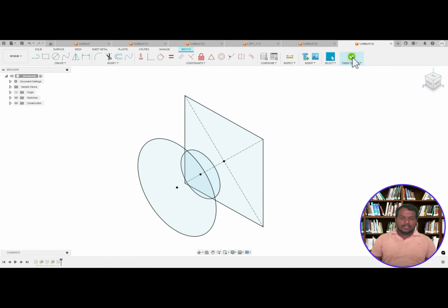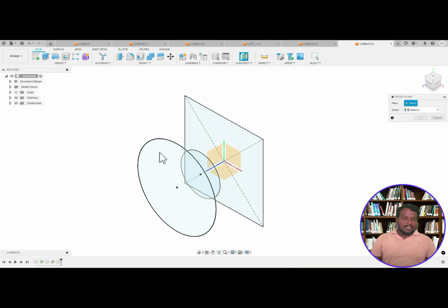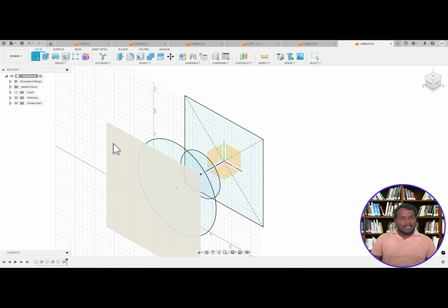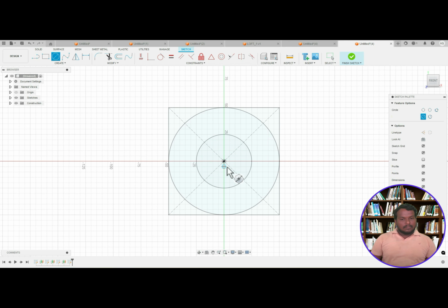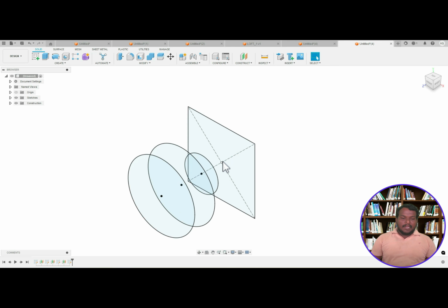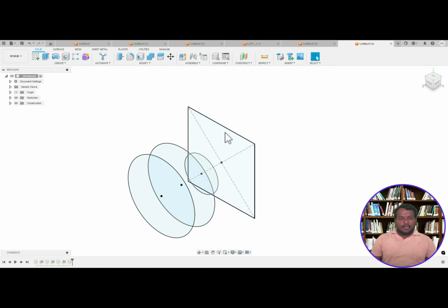Finish sketch. Next, create another plane of offset. Take the reference of this circle, and it is 30 mm. Okay. Next, create sketch. Select the plane. Another rectangle of 100 mm. Okay. Finish sketch. So I'm creating four, as per the diagram we have four profiles. First one is a rectangle, circle, circle, circle. Okay. So rectangle, circle, circle, circle.